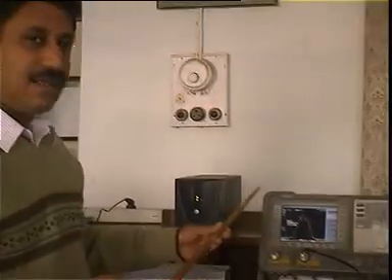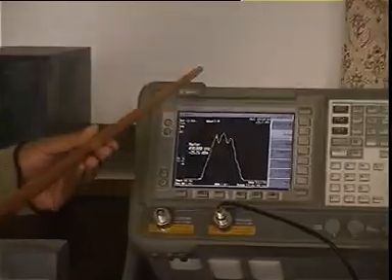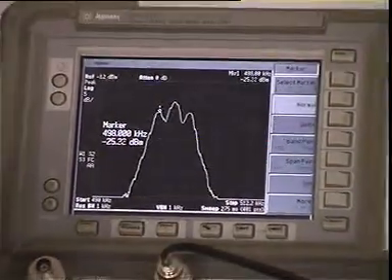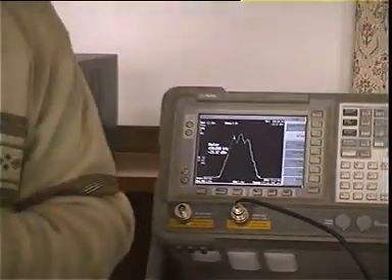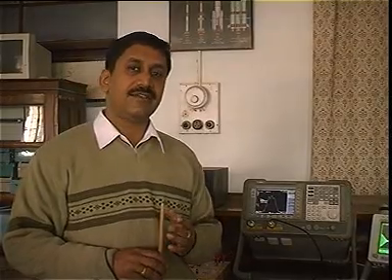So the AM signal will require twice the bandwidth of the modulating signal for it to be transmitted over a channel. Okay? So this is amplitude modulation with transmitted carrier. The carrier is also present. Very often we don't require the carrier to be transmitted, because the carrier by itself doesn't convey any information. On the other hand, it takes away a significant portion of the transmitted power. So it's not an efficient scheme.